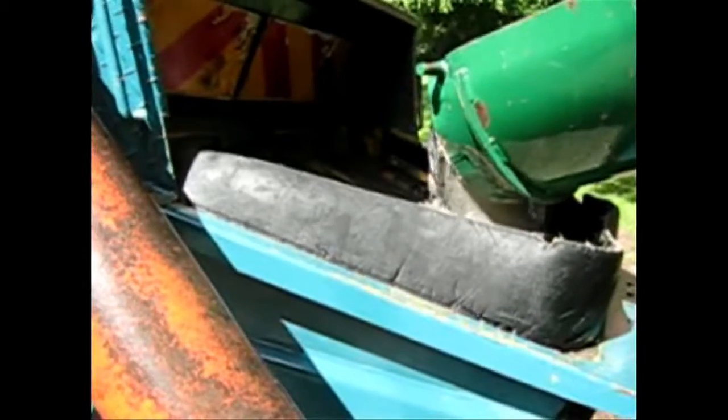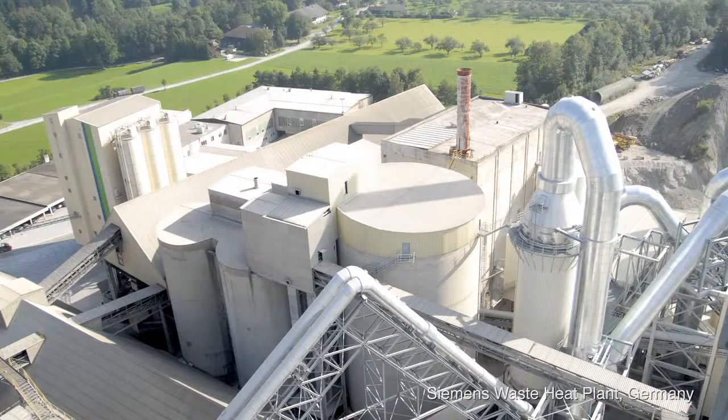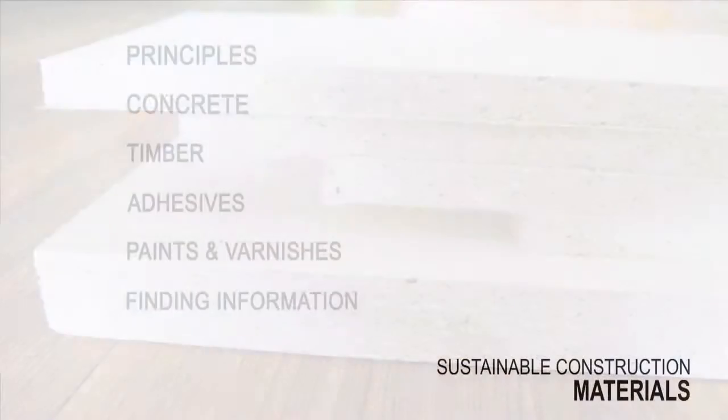Pre-mixed products are available that replace some of the Portland cement with industrial waste products. Replacement rates of 20 to 30% are easily achievable. Aggregates can also be replaced with recycled materials. Some manufacturing plants may use waste for fuel. There may be minor performance changes to workability and shrinkage, so check the manufacturer's instructions for working with these products. There are also new concrete technologies coming onto the market, like geopolymers that use aluminium oxide instead of Portland cement, and magnesium oxide products that can actually absorb carbon dioxide.